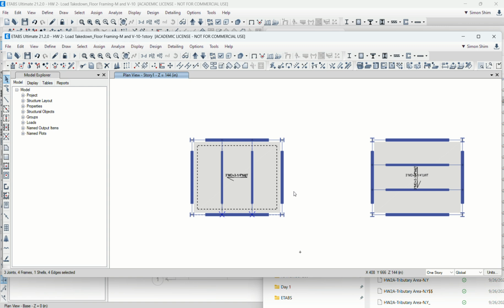You should actually observe what this arrow means. What does this arrow mean? Are they one-way slabs? Yeah. The metal deck is spanning one way, so it should be sitting on every beam, right? Because of that, it has to span between them. Basically, when we use a metal deck slab, we need a certain beam spacing, right?